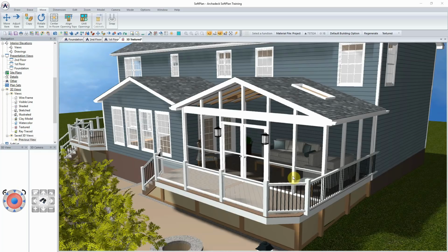And we will be able to, through a simple clicking of a checkbox, turn on the screened porch to show the client what that is going to look like. And then if they opt not to have it, we can simply remove that option and we'll be left with just the decks. This is much more robust than, say, layering, because layers are typically just whether or not you want to print an item on or off, but instead this is going to impact not only the construction drawings and the visibility there, but the elevations, the three-dimensional model, and even the bill of materials.